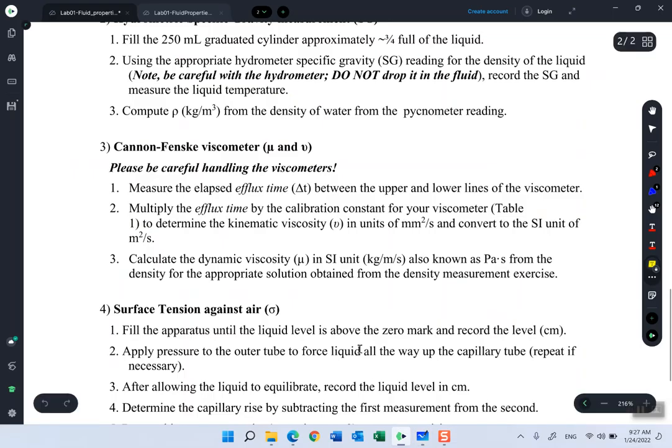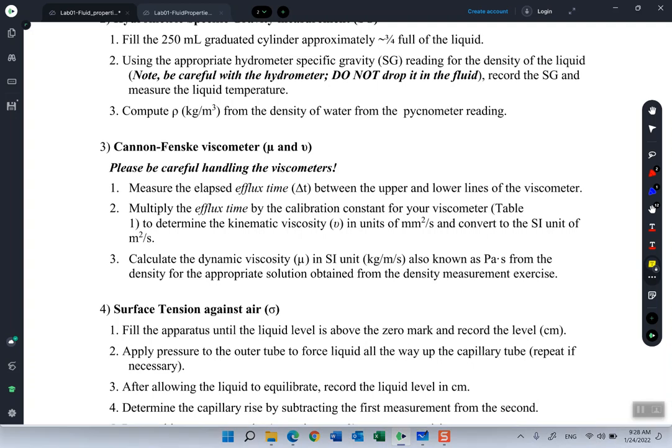So how are we going to measure the dynamic and the kinematic viscosities? I said earlier, we're going to use the Cannon-Fenske viscometer, and there's something I would like to express here, because it's really important, not only in this lab, but in every lab. You have to be really careful when you are using different units. To conduct a certain experiment and make the calculations, you should use uniform dimensions. And what I mean by uniform dimensions is, we know that